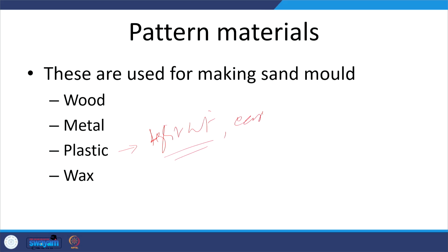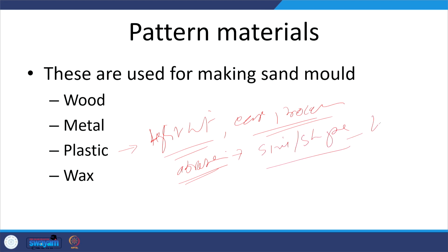Okay. And easy to process to get the desired size and shape. But the issue is the abrasion. You see, abrasion means when sand is continuously rubbing the plastics, so abrasion will be changing the size and shape. So, the life will be limited. So, the life is limited means we need to go for the frequent replacement of the plastic patterns, although these are not sensitive for moisture absorption related issues.